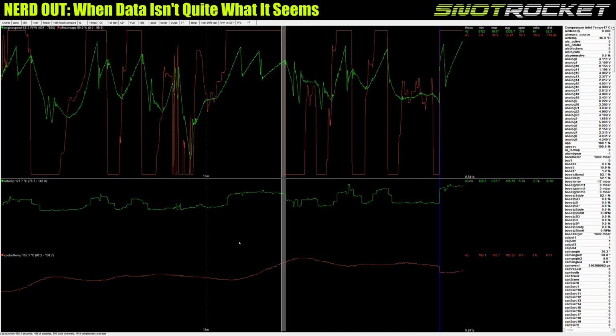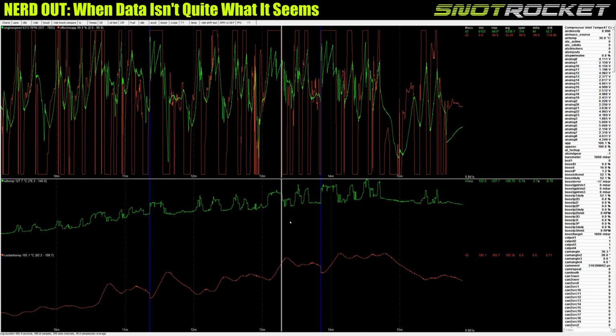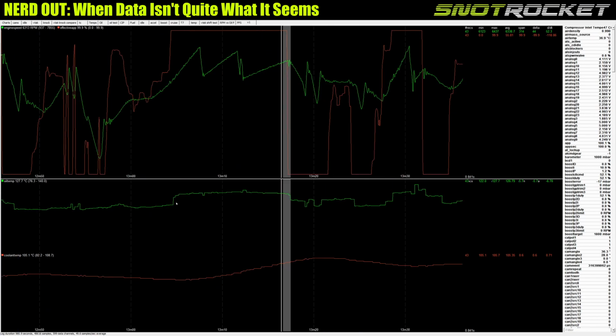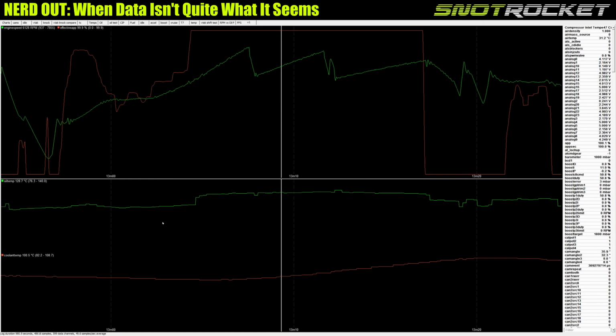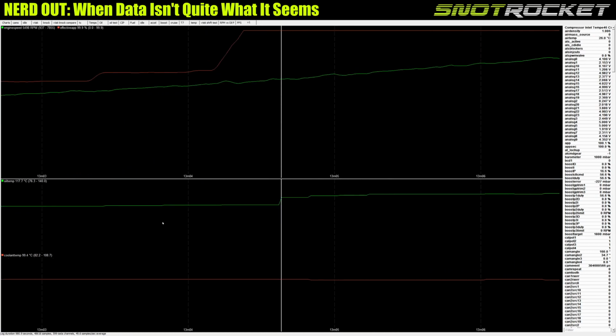So then looking at all of these spikes, you can see there's one here, there's one here, there's one here, and so on. I started to look at, well, what's common at the start of each of these spikes? What could be causing that? I wanted to see what was common. And if we look here, at where this spike starts, the engine speed is at roughly 5,500 RPM.